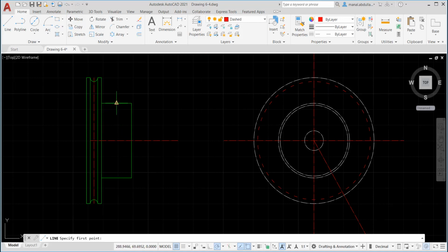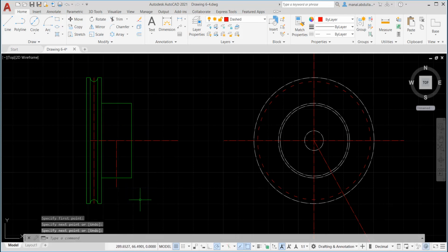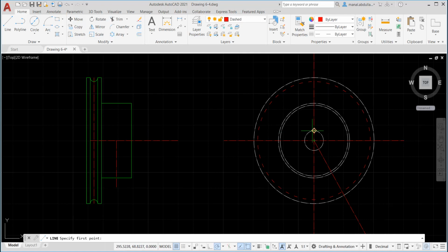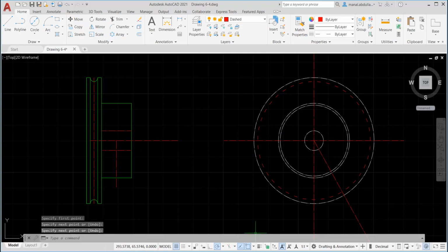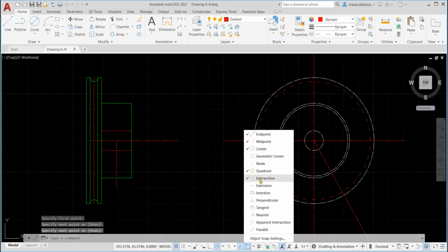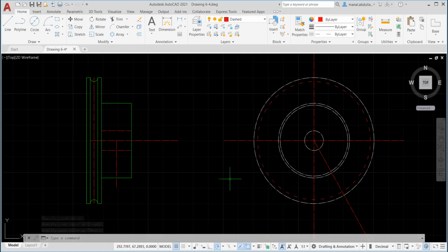So this is here again from the middle. Use the reference lines correctly, make sure it's vertical. So here you go. So we draw these lines here. After that, we need to grab some dashed lines over there. So let's go to line, and here you go. These lines here. Again, enter to repeat. Do not click. Just go over there, and when you get the intersection, be sure you have the object snap for the intersection to get this one. Okay, this is very important.